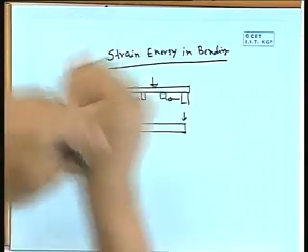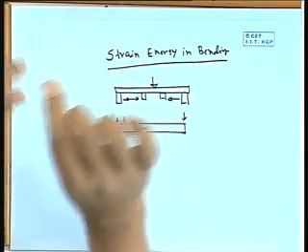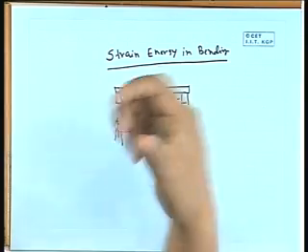Just shearing of the rivet, two plates with a rivet, if you try to pull, practically there is no gap, so it will shear. But if you place here, there is a long neck, two plates, so the whole thing will try to bend. So, it depends what is the size of our structure. Normally our structural member will have a large span compared to the depth. So, bending will be predominant, and normally we take the deformation due to the bending action.